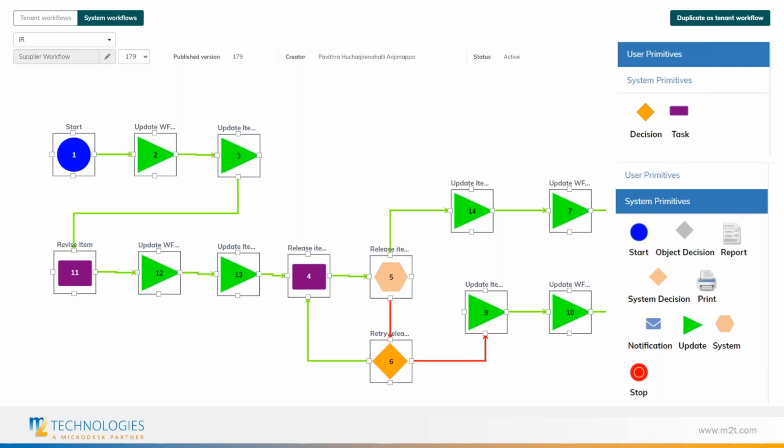This, of course, is built out by those primitives as we talked about. First of all, we have our start and our stop. These are included in every workflow as our creation point and our termination point of the workflow. We then have the notifications. These allow us to send custom email notifications to different users at different points within the workflows. We have the update. This is largely used to update the status of the workflow, so we can change the percent completed or its final status.